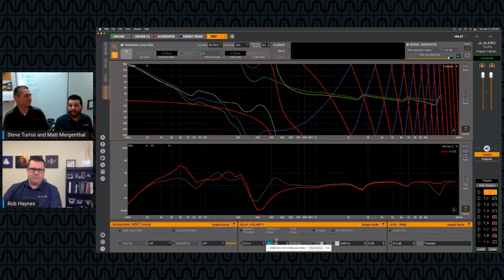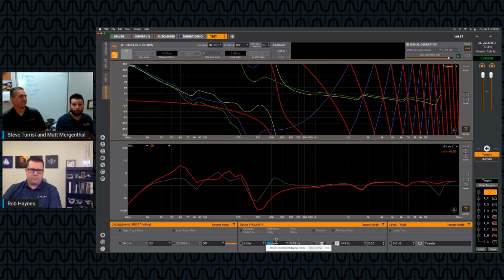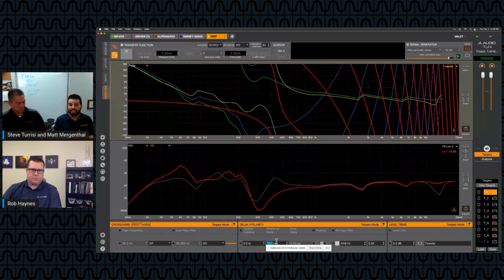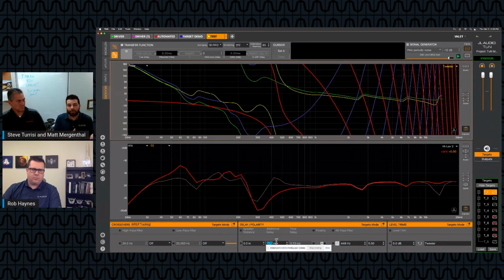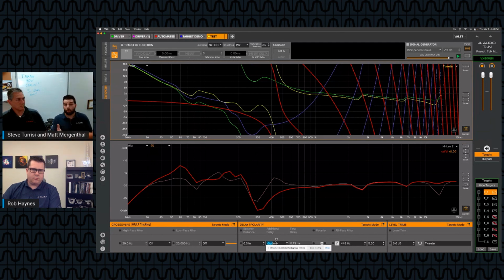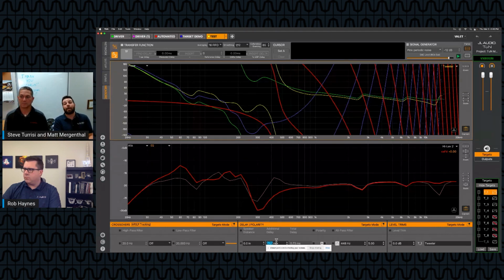We could take the radio out and put a new one in. That's super easy. Pull the radio, do something different. Another option would be to do a 2-channel input directly to the amplifier, bypassing the factory radio. So if you go with just a headphone jack or a Bluetooth, and you want to plug into your phone and go straight into the amplifier, that's an option.